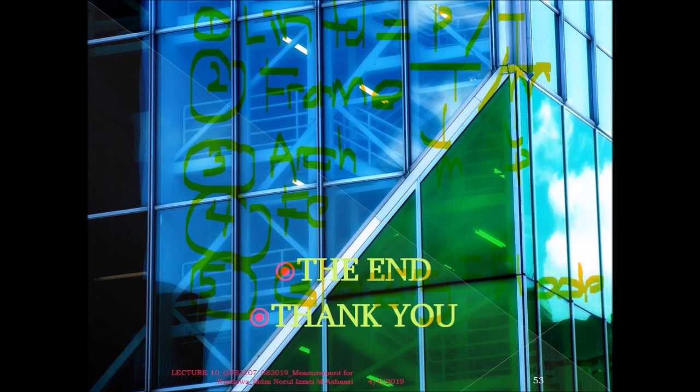And number 6, remember all types of window must require painting. The most important is painting for the frame and the painting for the casement. Okay, so the rest of information such as security bar, metal adjustable louvered frame, and then packing piece. Packing piece is required to be measured as well. Number 7, packing piece. And then any additional item, let's say you have roller shutter window, that one you have to refer to the detail properly. Okay, with that, thank you very much.